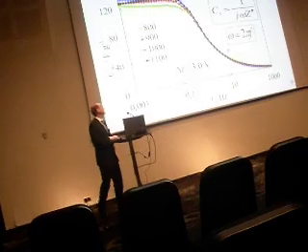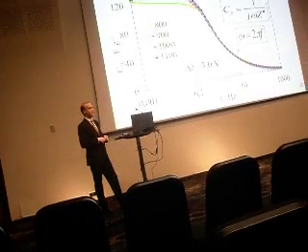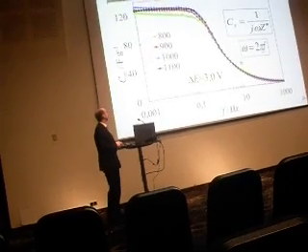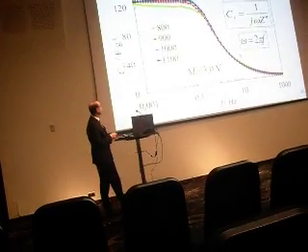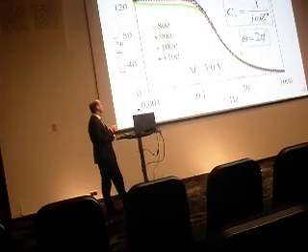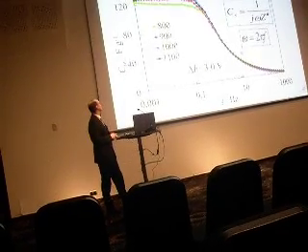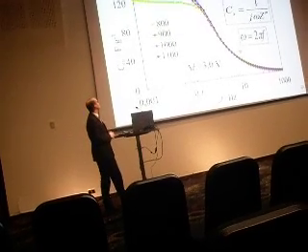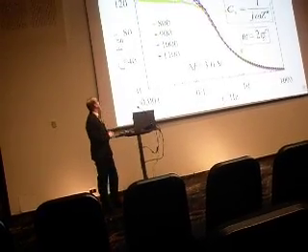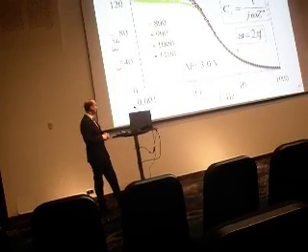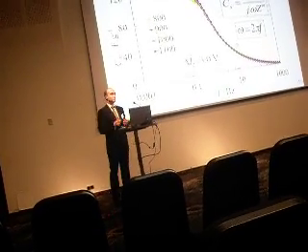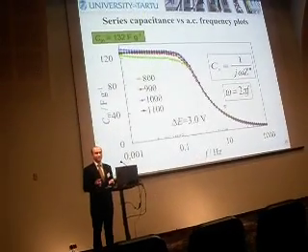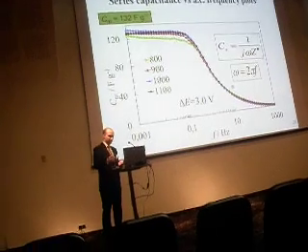And also from the impedance spectroscopy, the series capacitance that was calculated, you see that at about 0.1 hertz, the capacitance is about 120 to 132 farad per gram, which is about average for carbide-derived carbons.